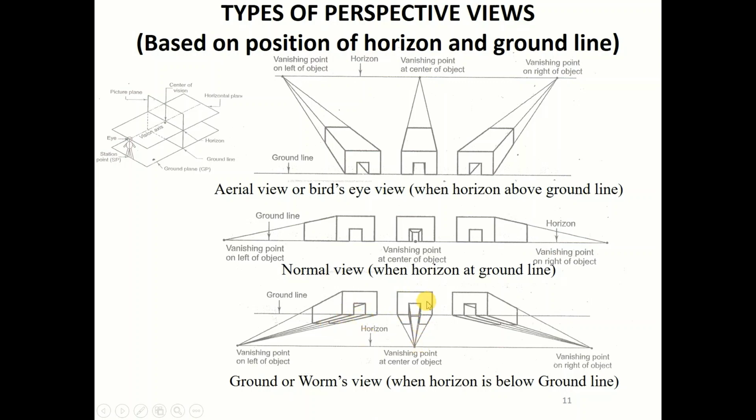In this case again you can see the front face and the bottom face, no left or right faces, whereas in this case you can see the front face, the right face, and again the bottom details. So you can't see the top face, you can see the bottom faces. In this case you can't see the bottom or the top. In this case you will only be able to see the top face, no bottom details.